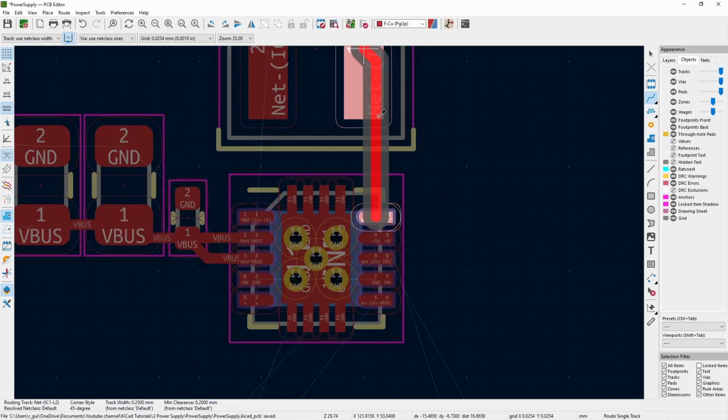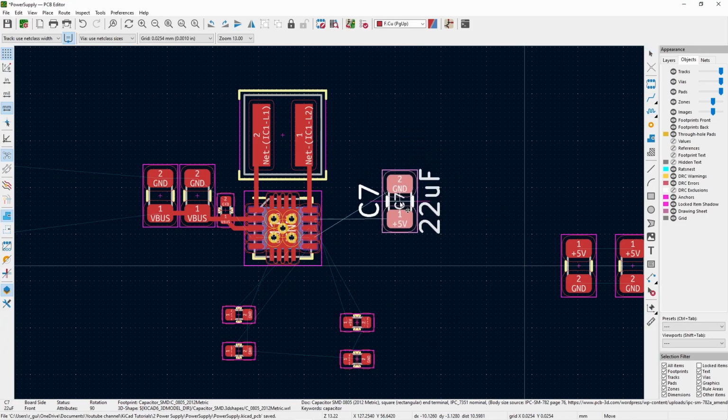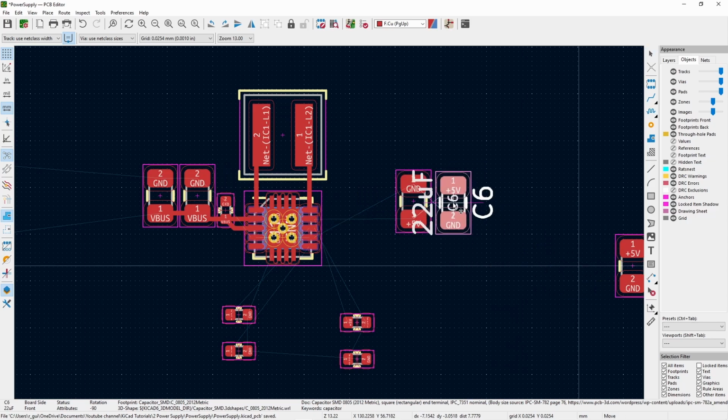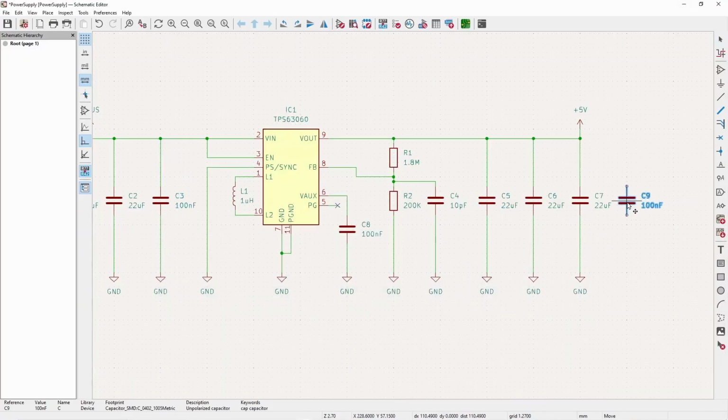Hello and welcome back. Today is an exciting day as I'm going to be doing a new project using KiCad. So I want to design a flexible power supply system for development that I can use on my videos going forward. So what I will be doing is designing a circuit, a PCB that can take in 5 volts from USB and give out a 12 volt power line, a 5 volt power line, and also a 3v3 power line.